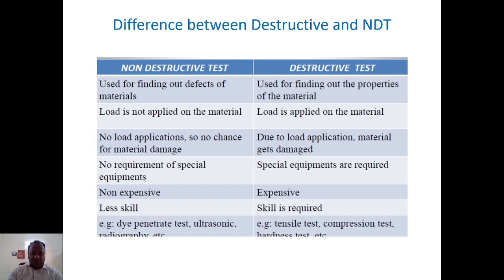So non-destructive testing is inexpensive, whereas destructive testing is expensive. In non-destructive testing, we can use less skilled operators. We can operate, test and inspect with a semi-skilled or less skilled person also, whereas skill is required in destructive testing. These are the ultrasonic, eddy current testing, dye penetration, liquid penetration and radiography, the non-destructive testing methods. Whereas in destructive testing, we can give tensile, compression and hardness tests. So these are the differences between destructive and non-destructive testing.